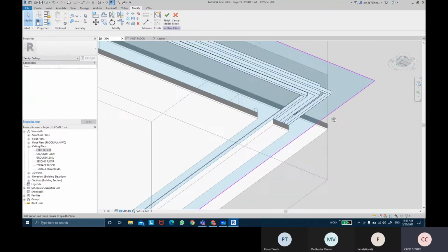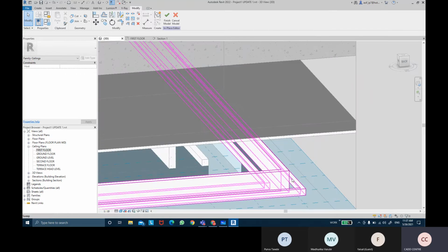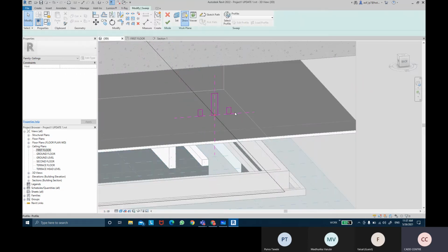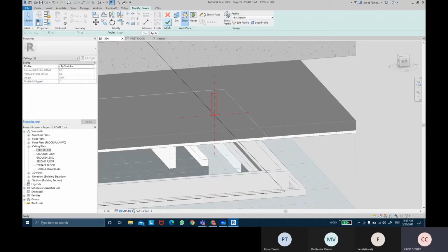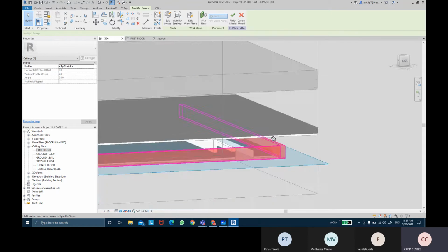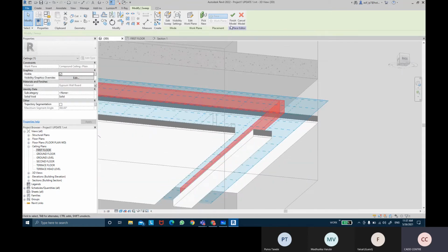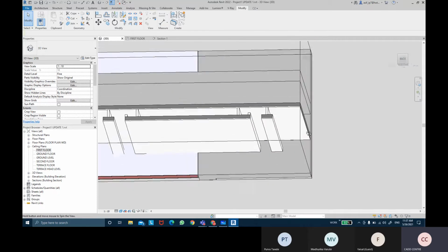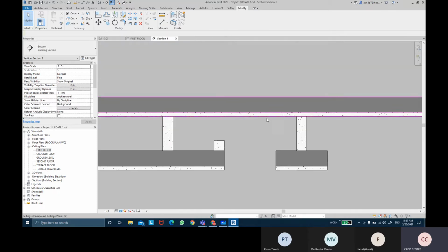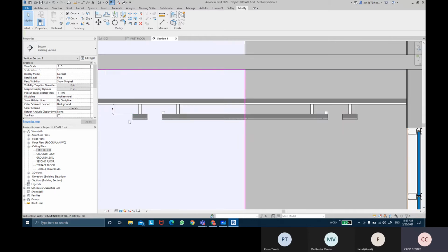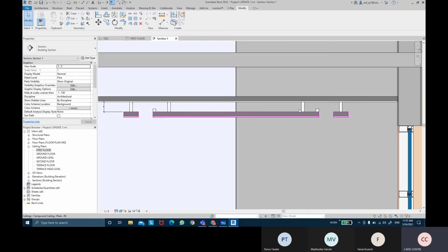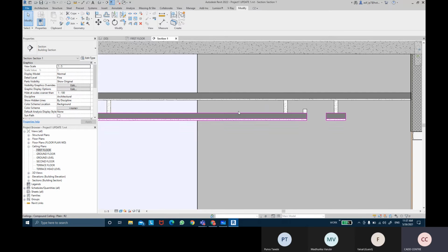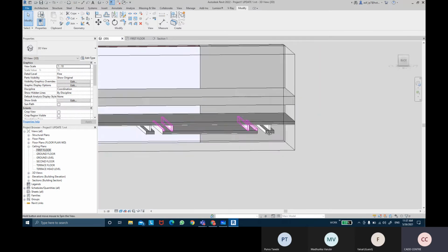So to fix that problem, what we gonna do is we gonna just once again double click and edit that profile. Not create these notches right now. Just create the center one first. Keep the notch separately. Do your section view. This is how it's gonna look. The only thing we need is the outer notches. So once again, same process for the creation of the notch.